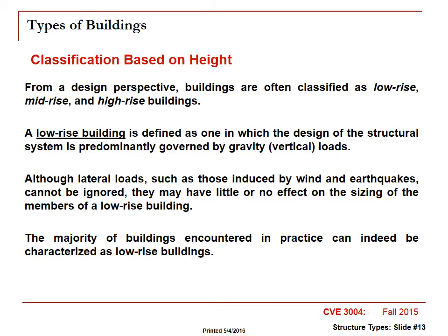And again, how they define a low-rise building for a certain type of analysis depends on what that method is. Sometimes, as we get into wind, a low-rise building is a building less than 60 feet, or high-rise buildings are over 100 feet or 160 feet. But it really depends on what we're talking about.